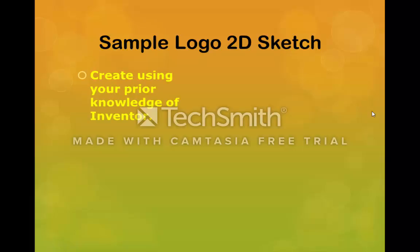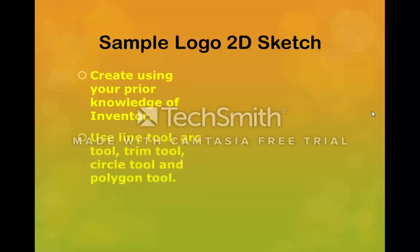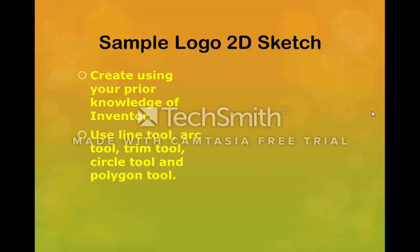While creating this logo sketch, you're going to use your prior knowledge of Autodesk Inventor. You're going to use the line tool, the arc tool, the trim tool, the circle tool, and the polygon tool. And you need to make sure you add dimensions as you do this. A suggestion is to use the metric system when doing this sketch. That way you're using decimals and whole numbers and you don't have to deal with any fractions while creating your lines and circles. Also, if you're going to do a symmetrical logo, think about how you can use the mirror line.